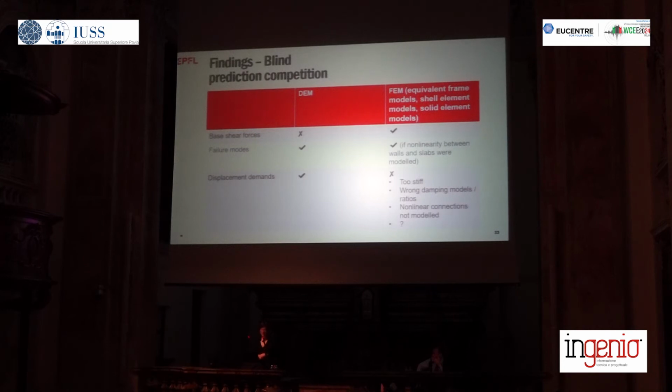They have underestimated the base shear forces. On the finite element model side, it's basically the opposite. They estimated the base shear forces well, but completely underestimated the displacement demands, as I said, mostly because the models are too stiff.